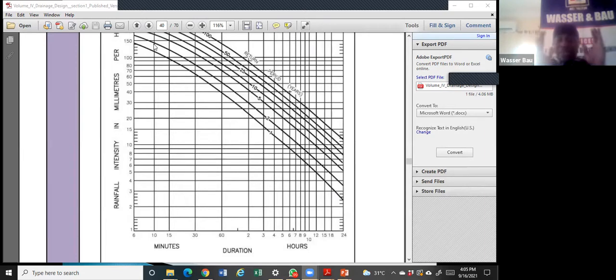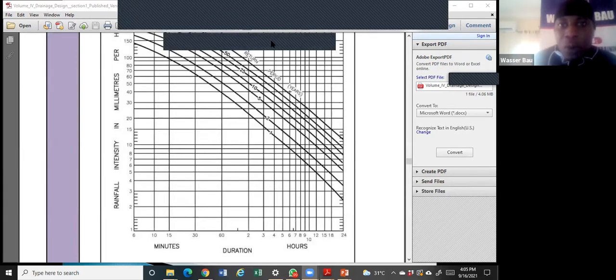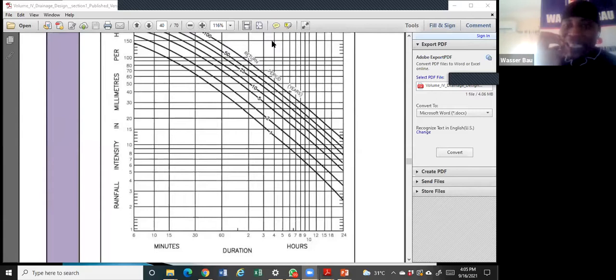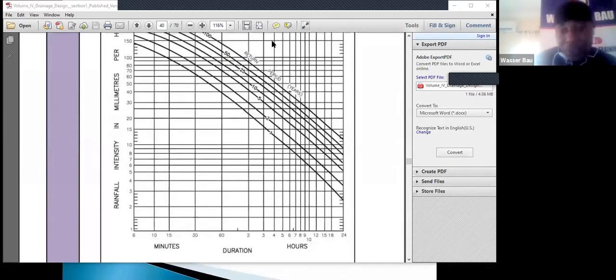You could see that the shorter, the more intensity it is. And let me just tell us this. In weather prediction, in all this CNN prediction we see on the news, once they measure the intensity of rain in the first 1 hour, they will tell you whether there will be flooding or not. That is the secret. If I measure the intensity of rain in the first 30 minutes, and it's giving me like 100 mm, then I'll blow alarm. That is how it is done.